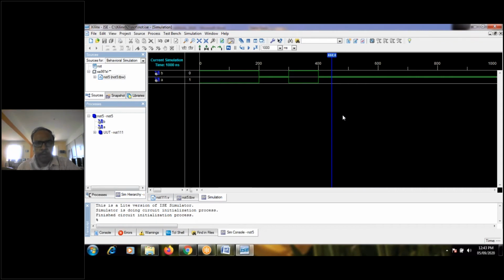In the lab, we are using the same thing, the same simulator. First we check the output with respect to the simulator for 3 to 4 programs. Once you are perfect, then you can check the same code on your Spartan kit, that is the FPGA kit.